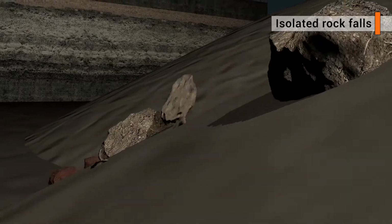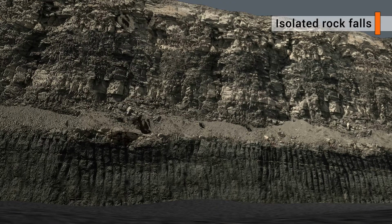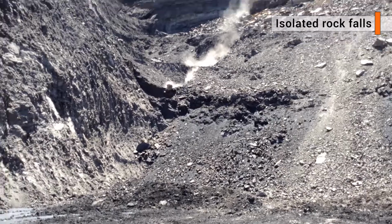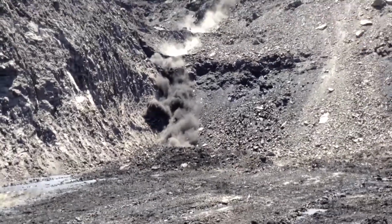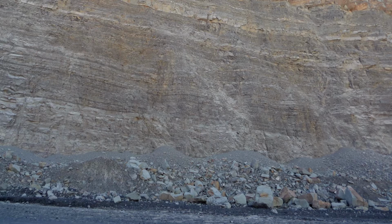Isolated rock falls. These are failures in which individual rocks fall out of a dumped or excavated slope face. Isolated rock falls can be just as hazardous as failures involving a whole slope face. They generally occur after heavy rain events, where poor separation of dumped material has occurred, or where blasting has been poorly executed and the face not adequately scaled for loose rocks at the time of mining.